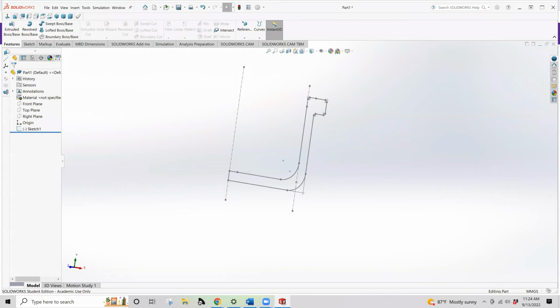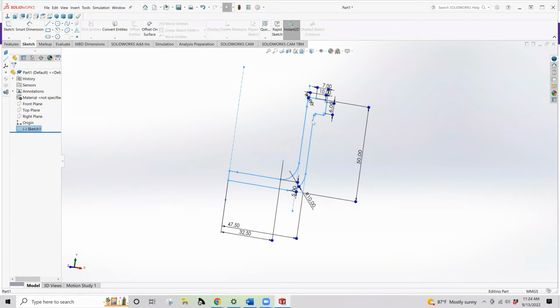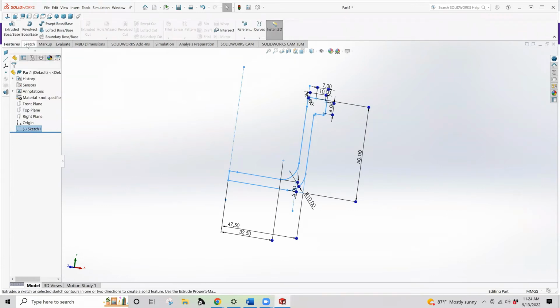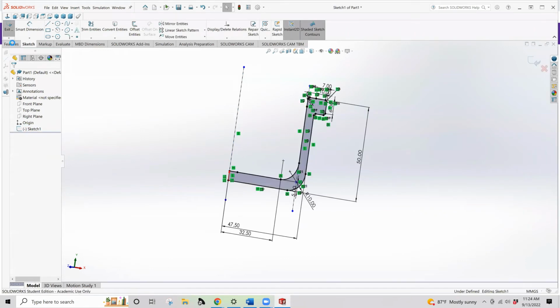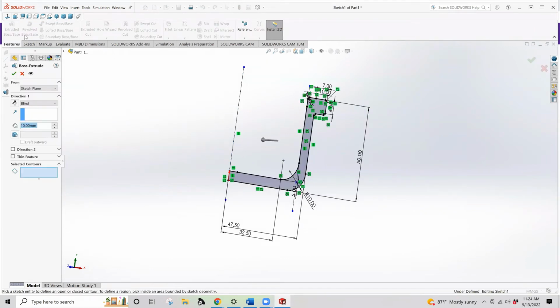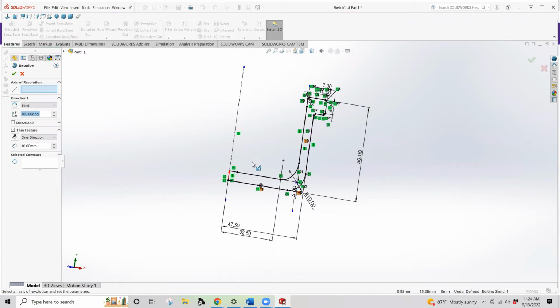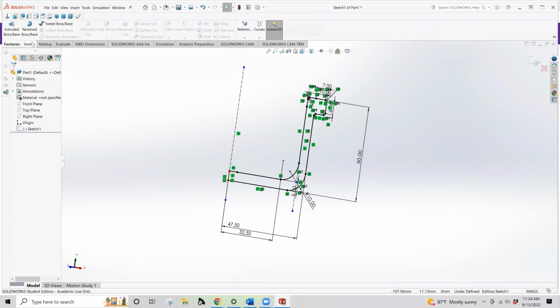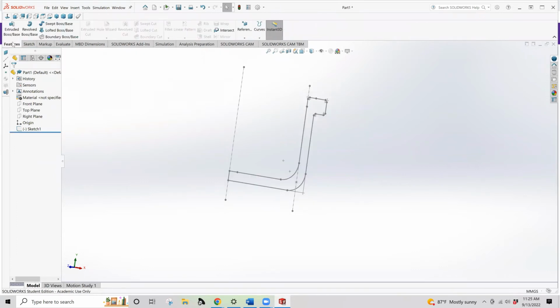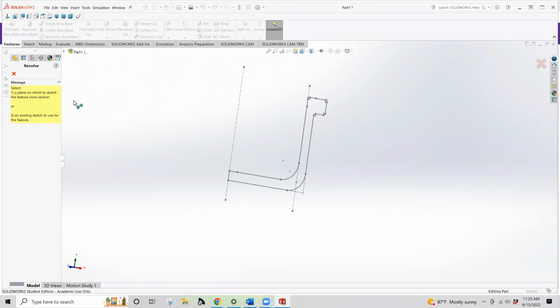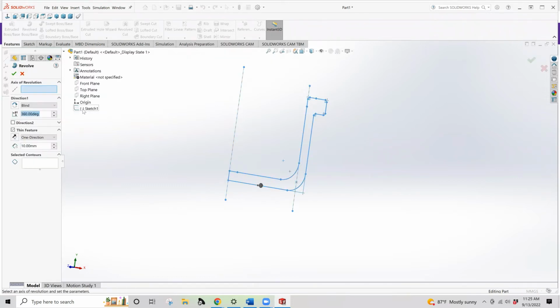If I were starting, I'm not coming from inside the sketch. There's a big difference between if you're in the sketch, you're editing. So if I go to edit the sketch and then I select the feature, not the extrude, but the revolve, it's going to assume that you're working in this sketch. It'll make some different decisions than if I step out of the sketch and I go to do a feature. Especially if you started with this yellow message, you want to get in the habit, again, of expanding the part tree and picking exactly what you want to operate on.